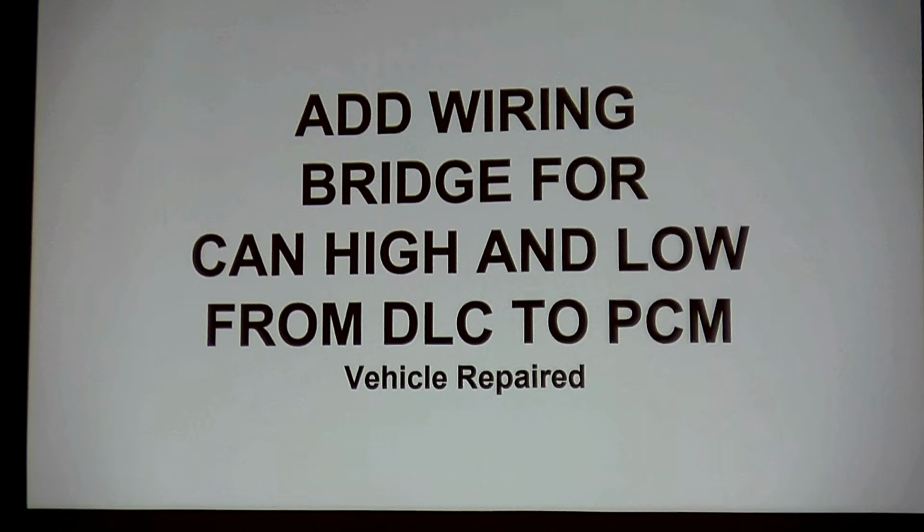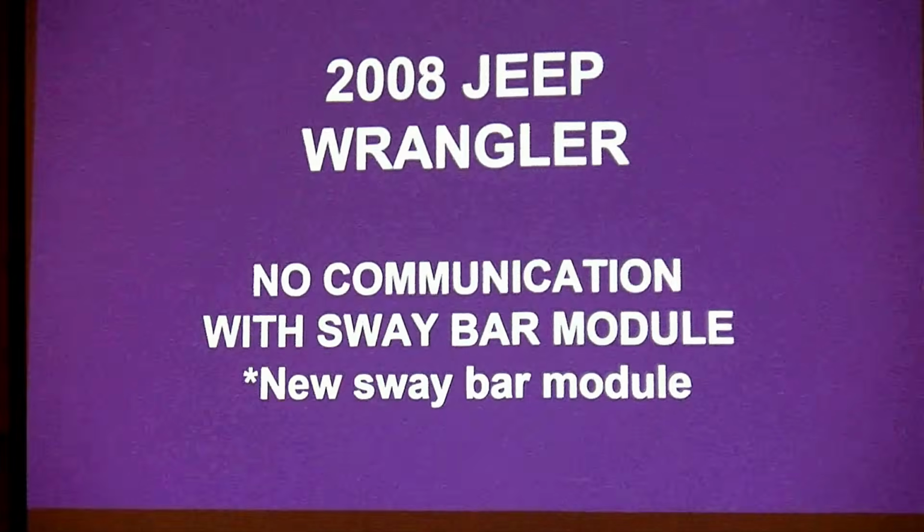You're allowed 3 feet off of stubs. That's part of the CAN standard. You're actually allowed 4. I cut it down 1. So they say 4 feet from a stub. I'm saying 3 and I'll be safe. They say I can stub into that bus. It's part of the standard. Why can't you? Works for me, and it's worked for many years.